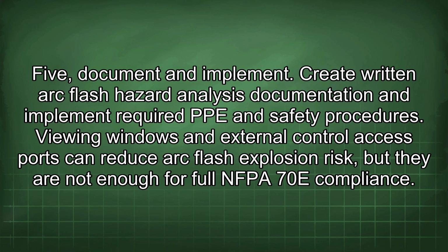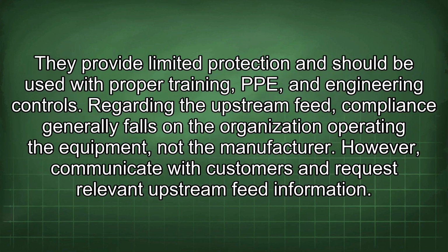Viewing windows and external control access ports can reduce arc flash explosion risk, but they are not enough for full NFPA 70E compliance. They provide limited protection and should be used with proper training, PPE, and engineering controls.